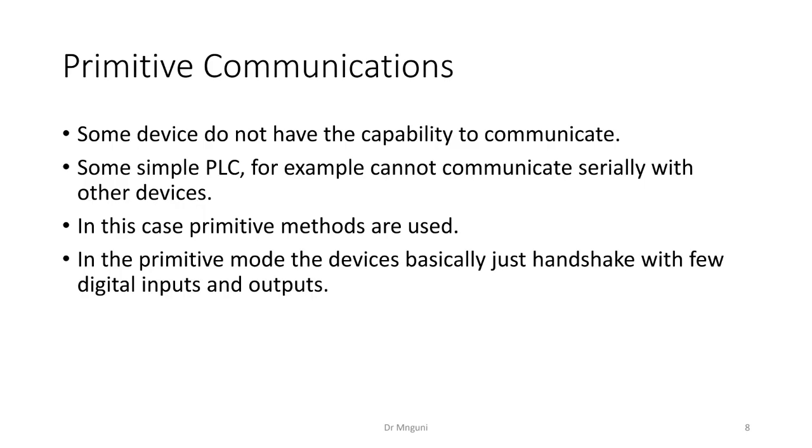Okay, which output 1 now? The output 1 that is coming from the robot, because the input of the robot was activated. And then once that is done, the PLC output can connect into that input 1 of the robot, and then the output 1 of the robot can be connected into another PLC. And now that process is simply called your primitive communication, okay? Where a PLC can command the robot to execute or not to execute, all right?